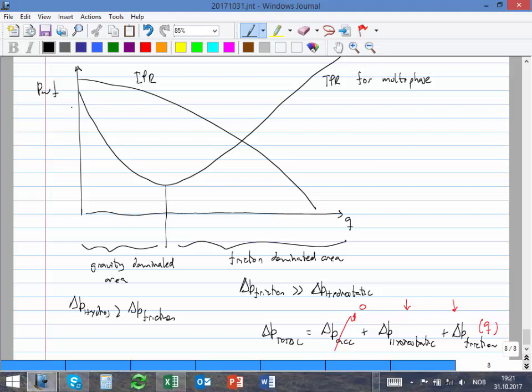But basically here the liquid is going very, very slow. So let's look at point number one. The liquid is going extremely slow in the pipe, and when the liquid is going very slow, the gas cannot go with it. They are like two friends who like to walk together to any place. But when one of them is going extremely slow, the gas just says, okay, I drop you and I go quicker. So because it goes very slow, the oil occupies